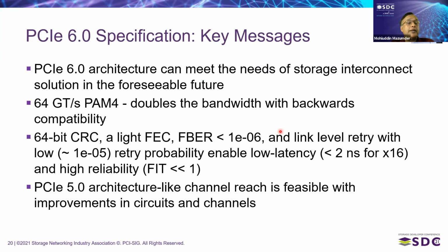It doubles the bandwidth with full backwards compatibility. We have seen and reviewed 64-bit CRC, a light FEC with first bit error rate less than 10⁻⁶, and using link level retry with low retry probability enables a low latency solution and highly reliable, with FIT much less than one.